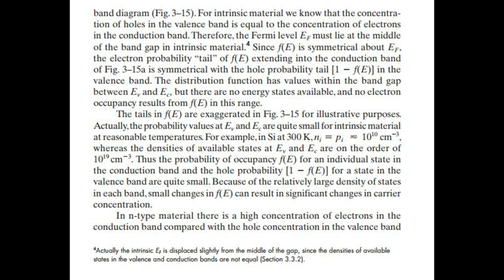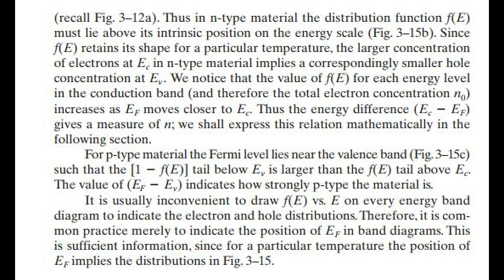In n-type material there is a high concentration of electrons in the conduction band compared with the hole concentration in the valence band, recall Fig 3.12a. Thus in n-type material the distribution function f(E) must lie above its intrinsic position on the energy scale, Fig 3.15b.